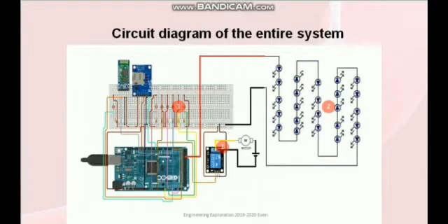Our project has a unique musical instrument known as the laser harp. It has 7 LDRs to play 7 corresponding classical notes of sargam, and it basically works like this: the 7 LDRs have lasers directly pointing towards them. So the laser pointing at the LDR outputs a very high analog value to the Arduino.